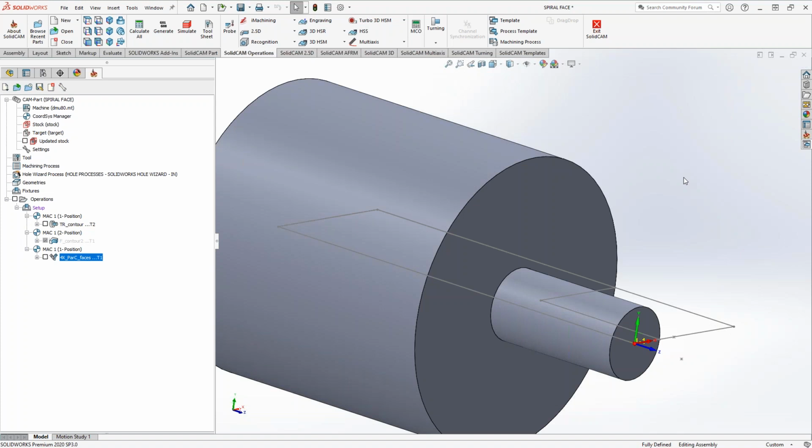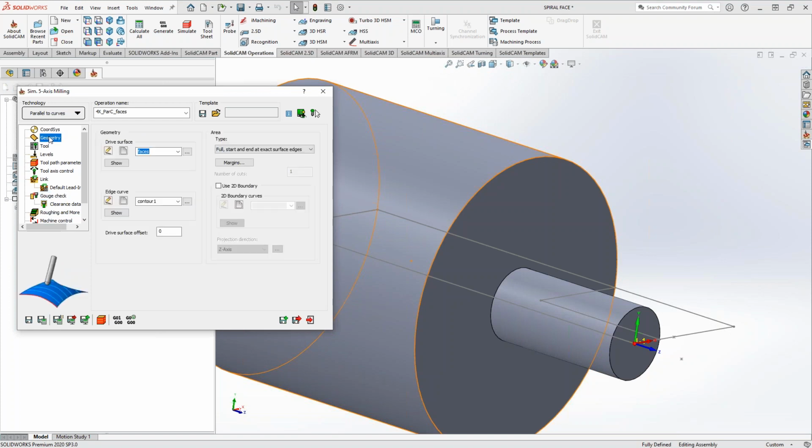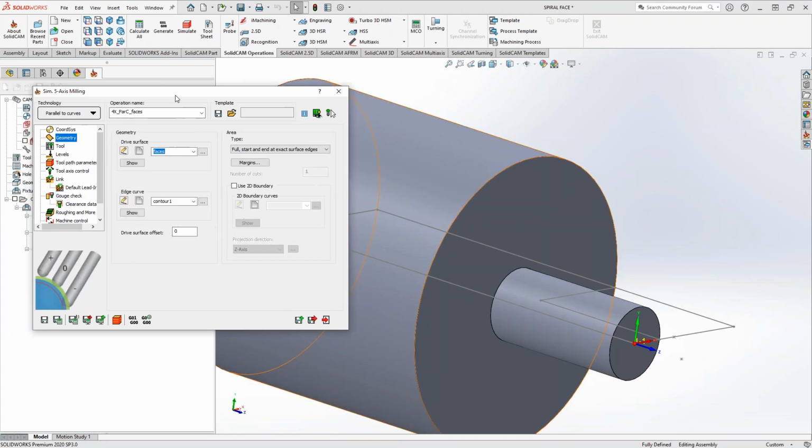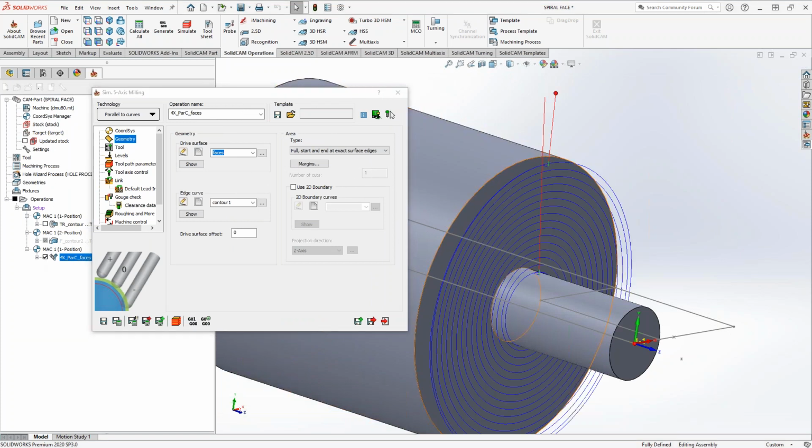If you're using this toolpath, remember that it's using surfaces and a contour. So the contour really just tells it which direction to go. In this case, I told it to be parallel to that curve. That's why we're getting that nice circular toolpath. It's just being parallel as it goes down. So Kevin's right. If we had a fillet or a chamfer or anything like that, or even if this was in a regular shaped toolpath, as it steps in the radial direction, it's just going to stay parallel to that circle. So it's actually going to give us that nice spiral all the way out.